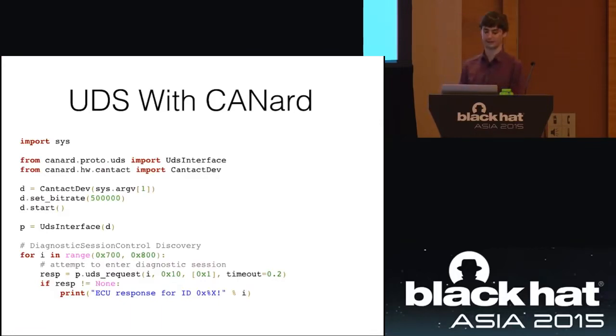So what this does is it starts up, imports some stuff, and then it's going to create a device. I used the CanTact device just to be different with this one. This is a direct access to this board rather than going through SocketCAN. The reason for that is you can sometimes have special features that aren't supported by SocketCAN, things like listen-only mode and doing hardware level filtering by identifier, stuff like that. So SocketCAN doesn't support it, so sometimes you might want direct access.